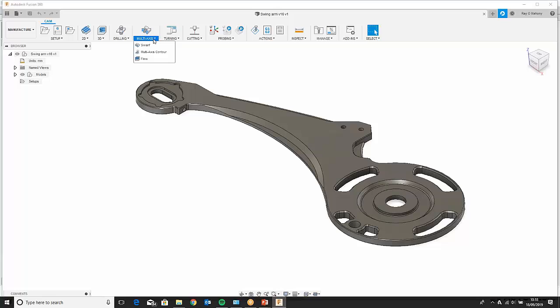There's one thing we'd like to share with you today: you have that flexibility, that freedom to explore that option, rather than just designing a component, sending it to the CNC machine, and then realizing maybe this is not the best strategy to go with. Maybe we can improve the part, remove a pocket or make a pocket smaller. In my experience, I've sent a part and found out there was a tool collision because the tool can't get down to a certain pocket or area.